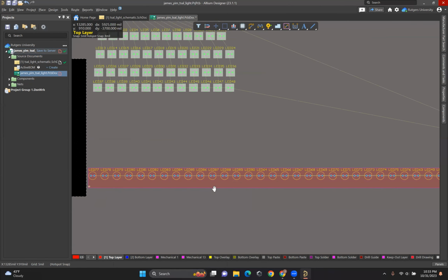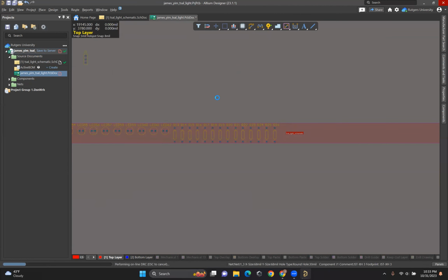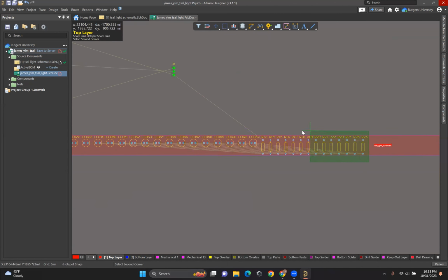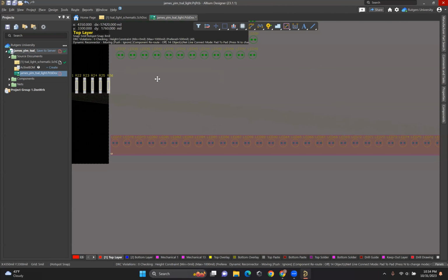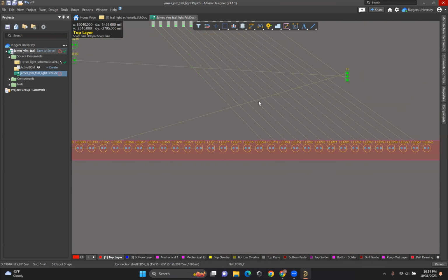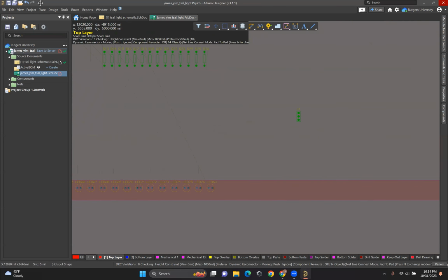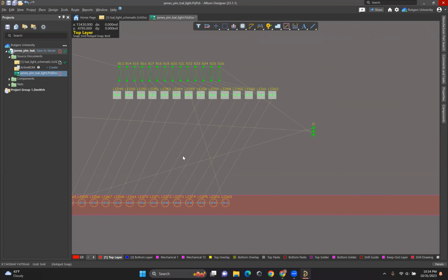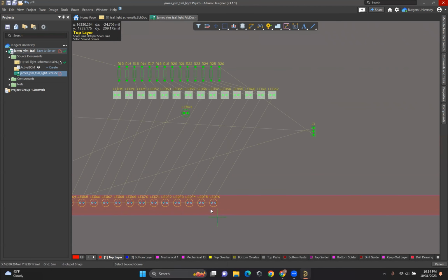Just moving everything over. This thing right here, the red box, it's called a room. I'm not really sure exactly what it's used for. I talked to one of the members, Mike, about it because he also was wondering what the purpose of it is. And we came to the conclusion that it's not super commonly used. That's what it's called in Altium. My understanding is it has more application in more complex boards, especially if you have a lot of daughter boards. But for our applications, I haven't ever had to use it.